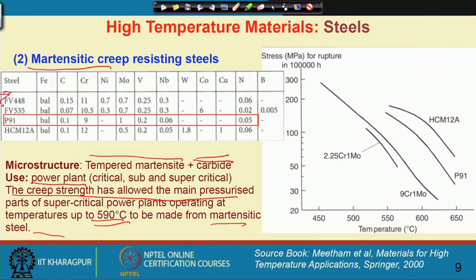You can see that the chromium content here in the martensitic steel should be lower than 15%. Here it is expected to be less than 12%, and those initial steels have a little niobium content. Nitrogen is not really a very good compound, because it forms nitride and brittle cracking. So, nickel is somewhat like 0.7 to 0.3. However, for this creep resistant steel we really do not need nickel at all.